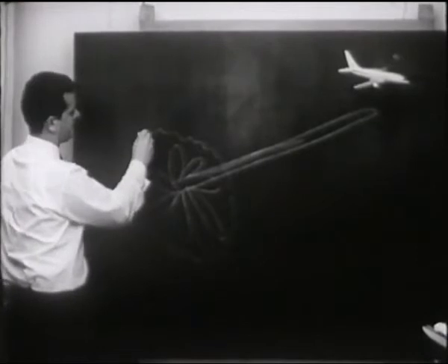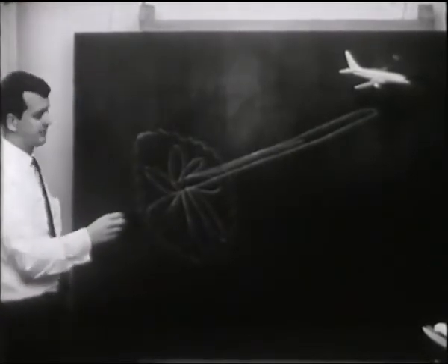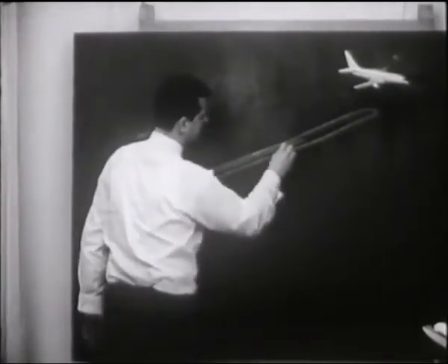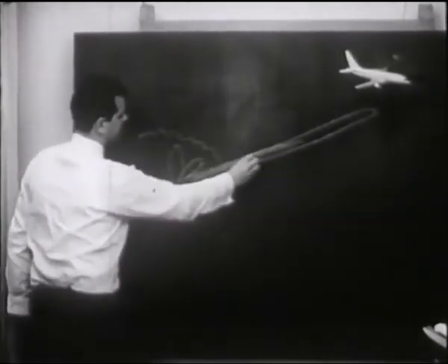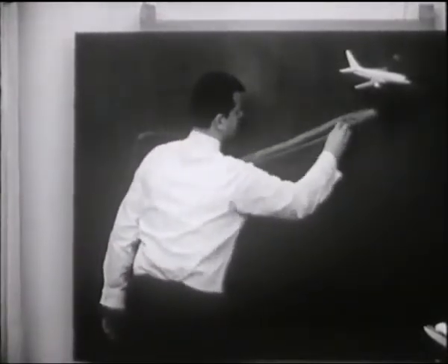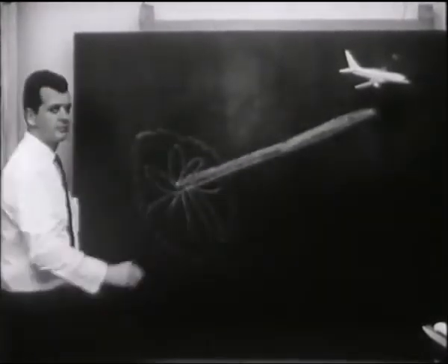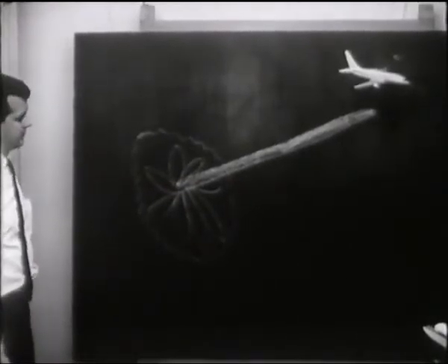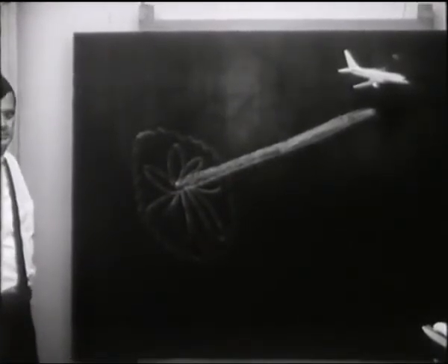The design of the airborne transponder is such that it will only reply when the interrogation is more powerful than the omniradiation field. And this is only the case within the main beam of the SSR interrogator antenna. This technique is termed side lobe suppression, SLS.